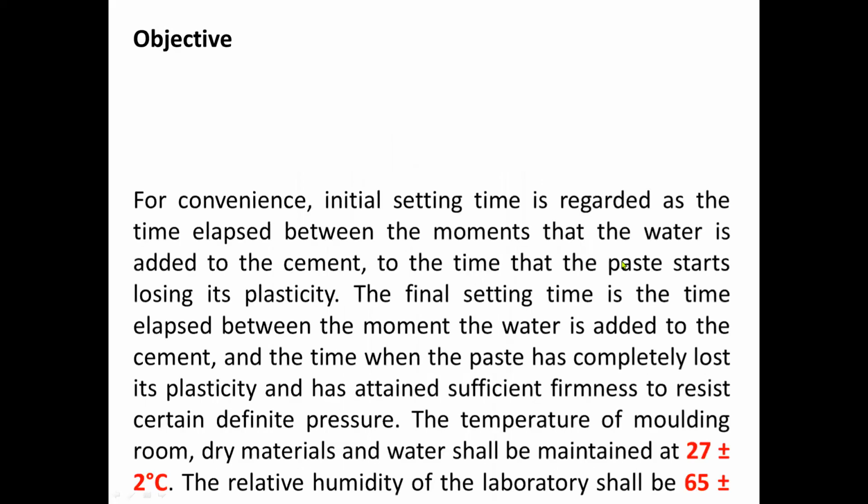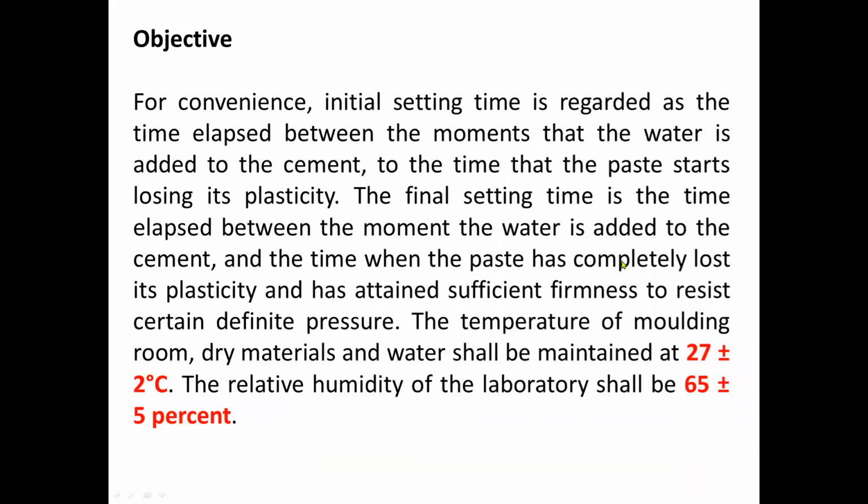For the objective of today's lesson, for convenience, initial setting time is regarded as the time elapsed between the moment that the water is added to the cement and the time that the paste starts losing its plasticity. The final setting time is the time elapsed between the moment the water is added to the cement and the time when the paste has completely lost its plasticity and has attained sufficient firmness to resist certain definite pressure.